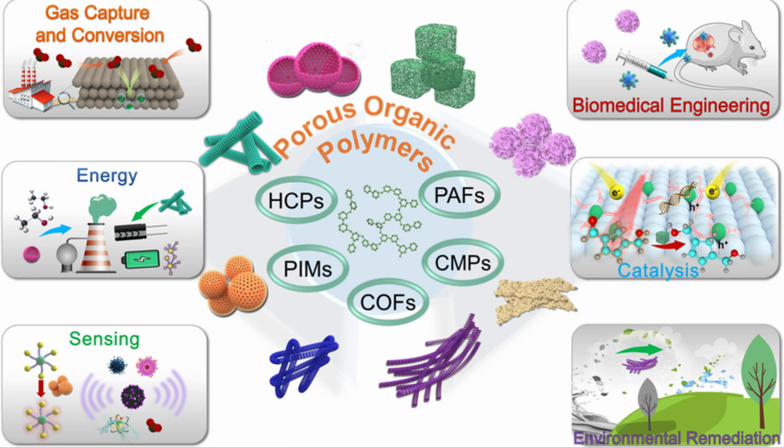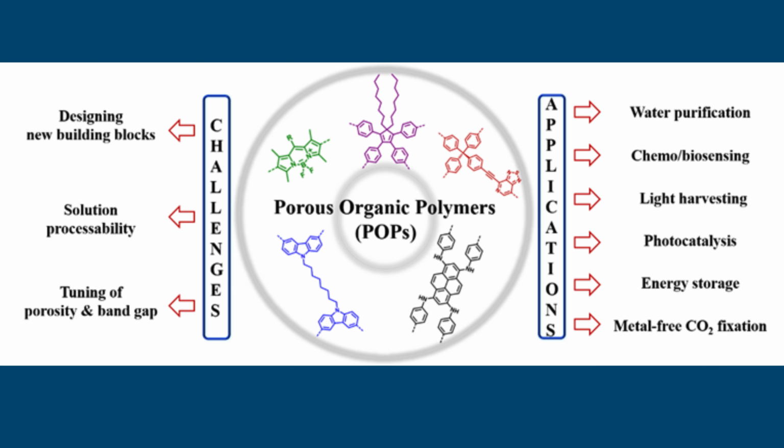This video report provides a comprehensive and descriptive overview of porous organic polymer structures, fabrication methodologies, and emerging applications. Structural characteristics are discussed in terms of pore size, connectivity, and polymer skeleton architecture. Major fabrication strategies, including electrospinning, phase separation, gas foaming, freeze-drying, breath figures, and templating, are critically examined with respect to their underlying principles and resulting morphologies. The relationships between pore structure and functional performance are highlighted across diverse applications such as sensing, thermal management, electromagnetic shielding, separation technologies, and biomedical systems. Finally, current challenges and future research directions are discussed to guide the rational design of next-generation porous polymer materials.